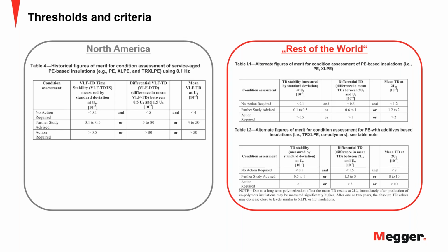Yeah. Well, I just want to say the IEEE is a true standard. It's not a guideline. The IEEE for tan delta, as well as for hipot testing or withstand testing, is a true standard. Compared to, just to point that out, that difference, when you go to partial discharge testing in the field, the 400.3 from IEEE is a guideline. Okay, that's a big difference, because guideline gives you guidance, and the standard means you must adhere to it.